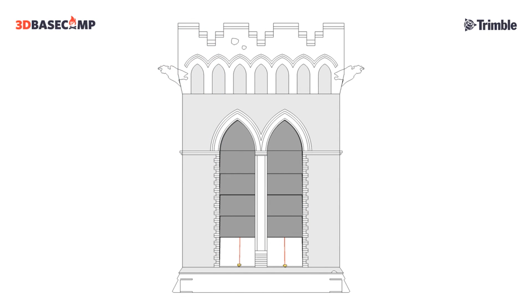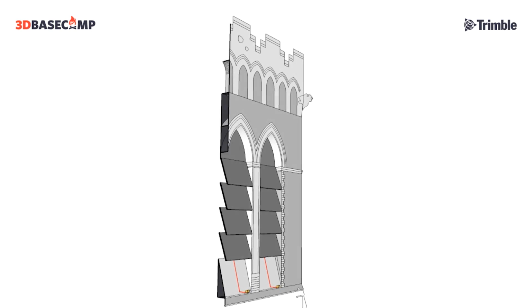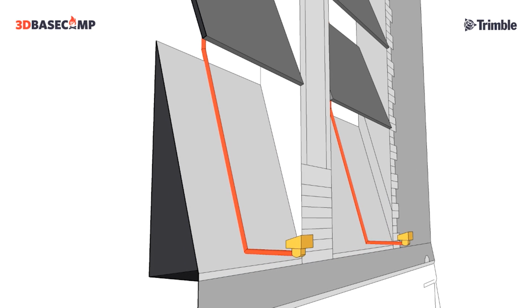And this all started from the CAD file, so this was just the basic CAD file that was brought into SketchUp, extruded out, cut away for the section, and then using Follow Me to create the conduit, and then just using the photos and kind of the dimensions of the product just to quickly model it as a fixture. So again, a pretty quick way that you can kind of illustrate an idea without having to invest a lot of time and technical sort of detailing in that.